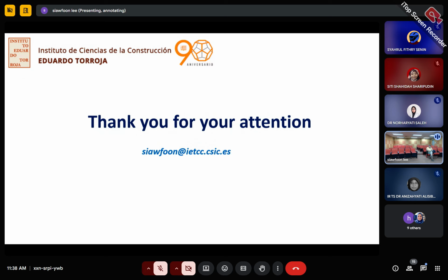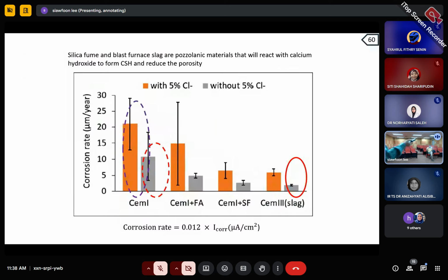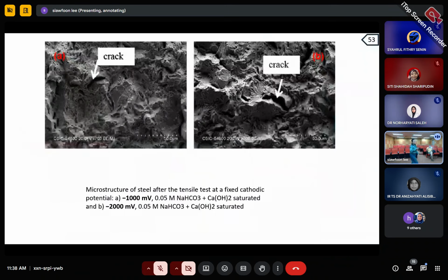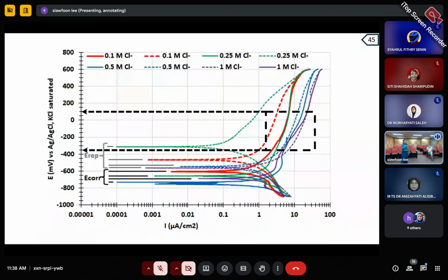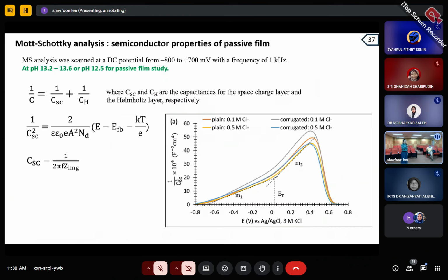I mean, when you reach pH 8, the passive film doesn't form on the steel, which means you don't have the defense anymore. Your enemy is the chloride ion. So when you don't have the defense, your enemy can just enter so easily into the steel. In one of the slides I showed you, this is the pitting corrosion, the very early slide. Let us go to that.